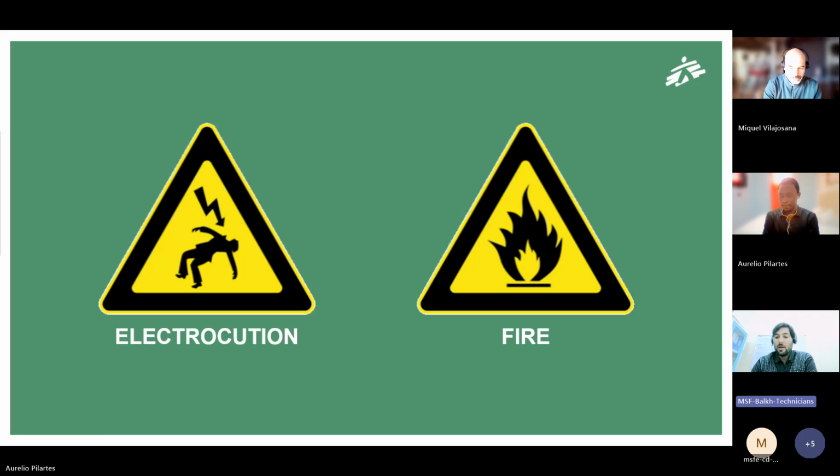we have RCD breakers, as you mentioned previously. And also for fires, if we do not select the proper size of the MCB breakers and MCCB breakers and also the cross section of the wires, a fire will happen. So for preventing fires, we need proper cross sections for electrical cables and wires, proper sizing of our breakers, and also selection of the type of the breakers. So I think that's all from my side.